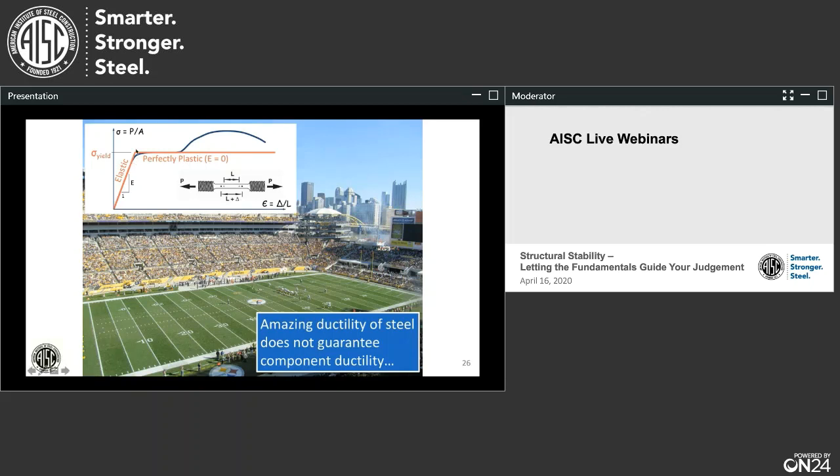If we get to yield on this football field, that is the 1 yard line. So we've only moved 1 yard. Then we come across the yield plateau, and we're at the 10 yard line. And then it's quite interesting. All the way over here looks like the Hail Mary pass, literally to the other end zone. So this is really, when you put things to scale, how much ductility steel has. It's amazing. It's a very, very ductile material, very high strength, excellent properties.